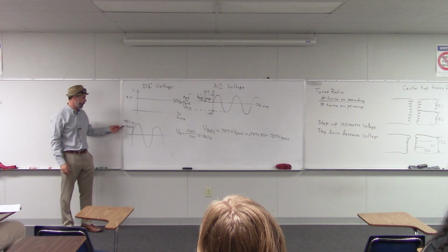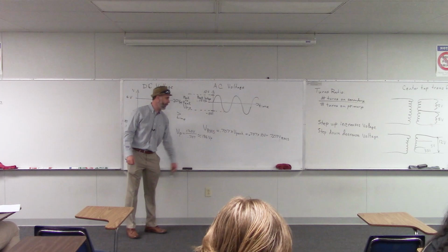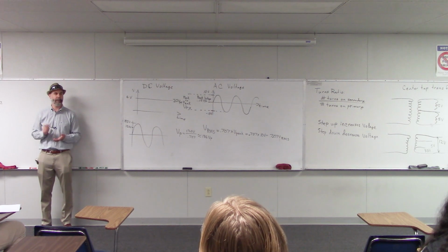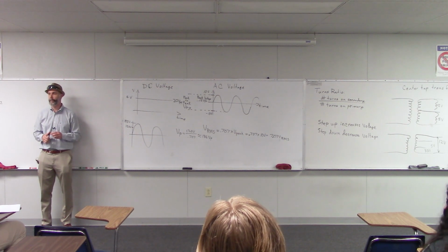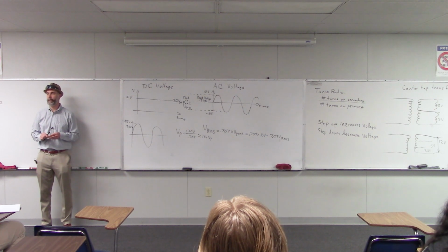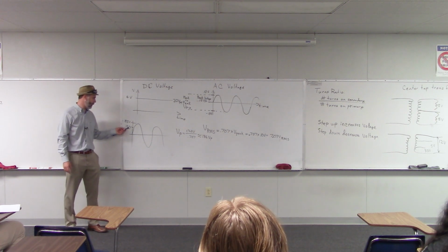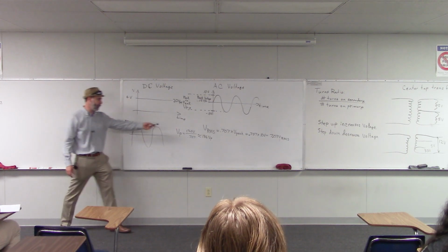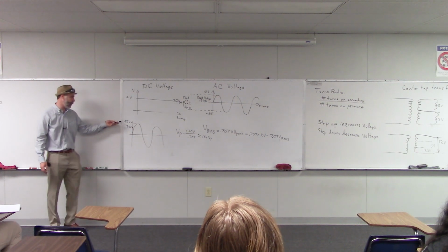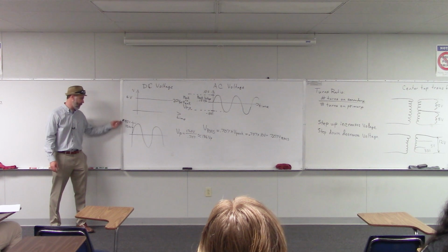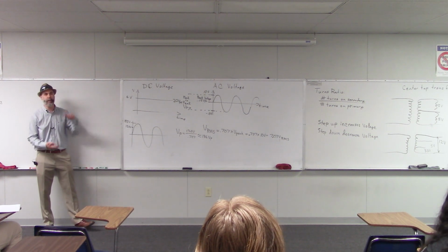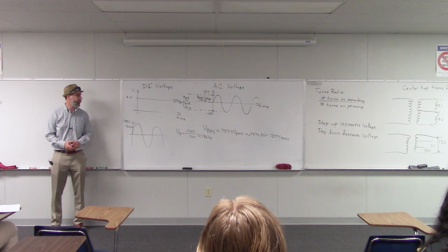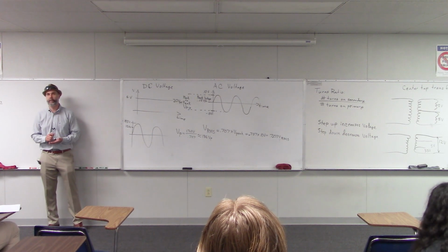But we think of it as 120 volts because that's what it is, RMS. Okay? So it's just a weird standard, but that's what's used most commonly. Yeah? You said this is when talking about voltage coming out of the wall. Yeah. So when we talk about the common power that we have in our walls, we say it's 120 volts. But that's 120 volts RMS, which means 185 volts or so peak, which is the same as saying about 370 volts peak to peak. Okay? So that's what's going on there. So questions about that? Yeah.